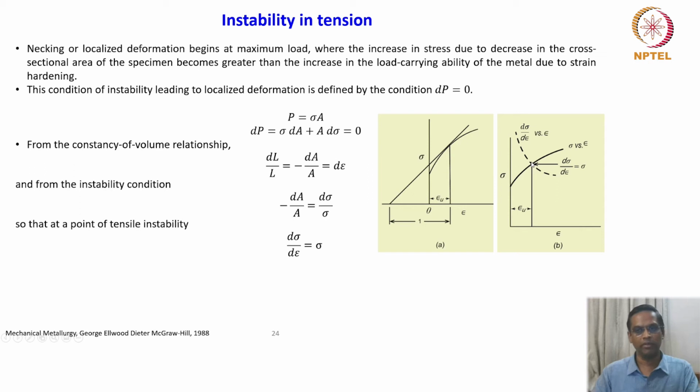Okay, so this is very important, right? And you can also check this in your simple tensile test. You can plot these two things: work hardening rate versus strain, and stress versus strain. You will be able to see that the maximum UTS will match the point where d sigma by d epsilon is at its lowest value. So you will see that.